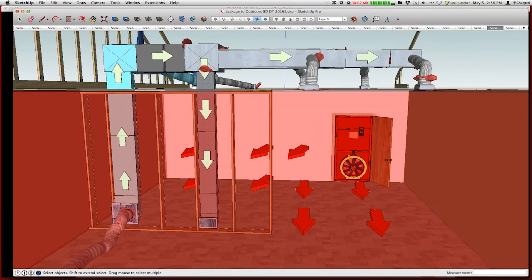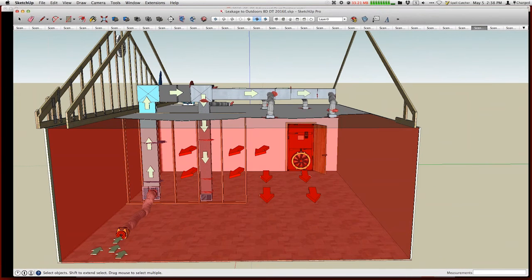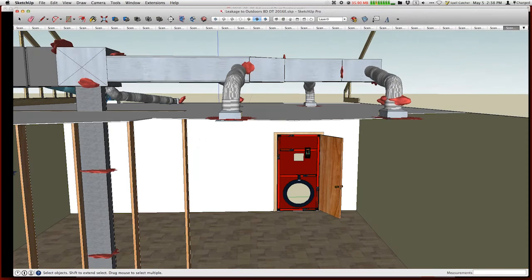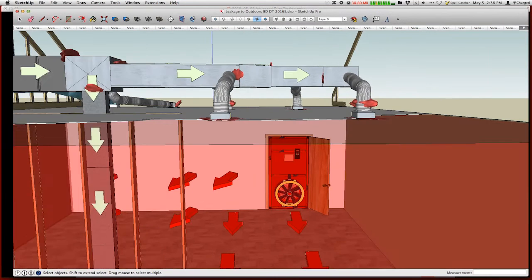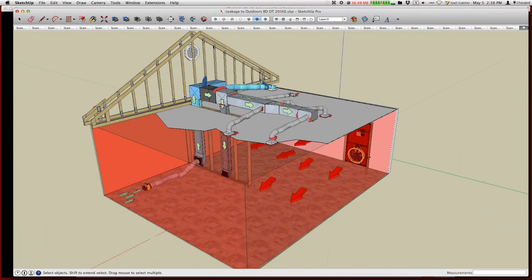I'm going to activate the blower door first. It's going to create a pressure throughout the inside of the house. All right, I'll do that again because I think it's pretty cool. So it'll create a pressure inside of the house, and now I can activate the duct tester. And what's happening now is that all the pressure that's inside the envelope is also now being isolated. So I no longer have leakage to the inside. So this leakage you can see here, right there in the middle on the ducts that are vertical, that's actually now gone.